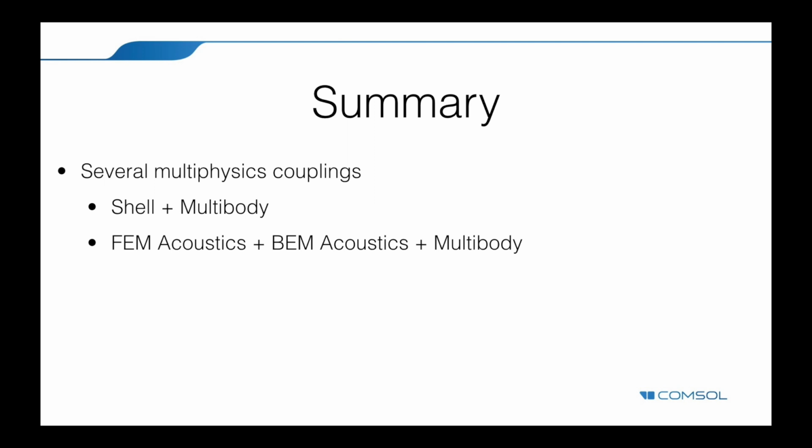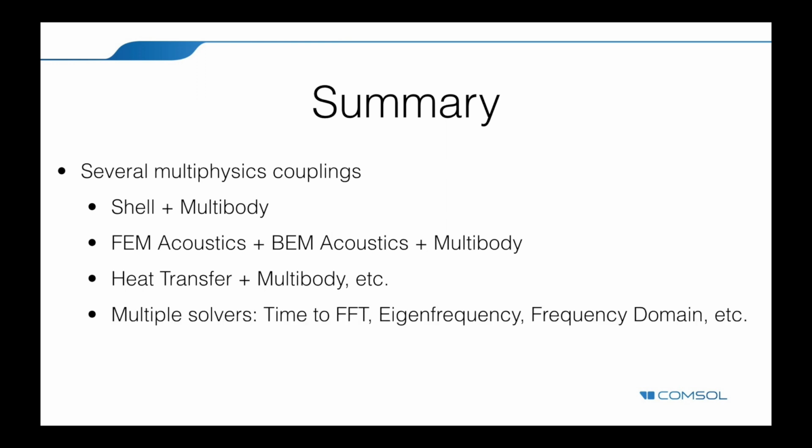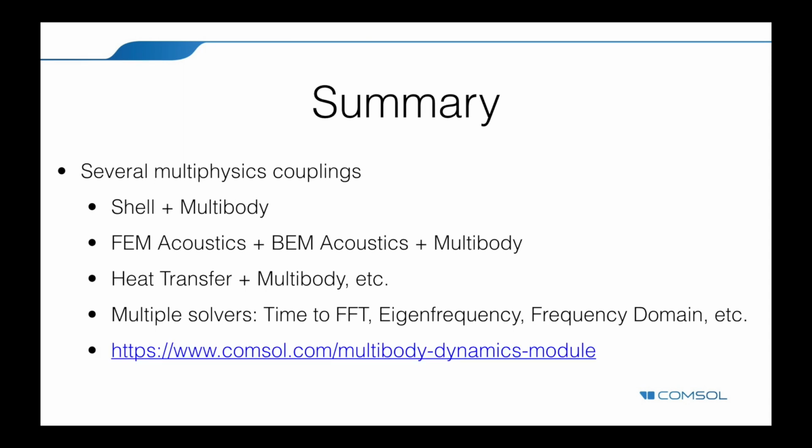You can include heat transfer and whatever you can imagine, so you can expand the capabilities of the Multibody Dynamics module. And there are different types of solvers, so you can solve in the time domain, in the frequency domain, and you can calculate between these domains back and forth quite easily.